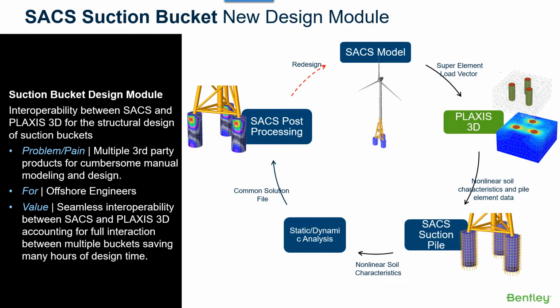The next update is to design the suction bucket foundation. This feature is included in this official release from technical preview last year. A typical workflow is to model a structure including the FE model of the suction bucket, then export the super element, which represents the stiffness of the jacket structure, and also export the load vector and suction bucket model so that Plaxis 3D calculates a series of nonlinear springs that will be automatically imported back to the suction bucket model in SACS.